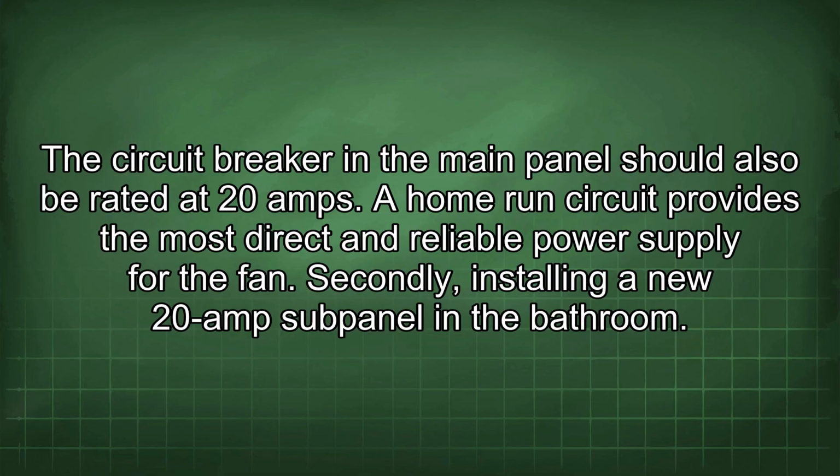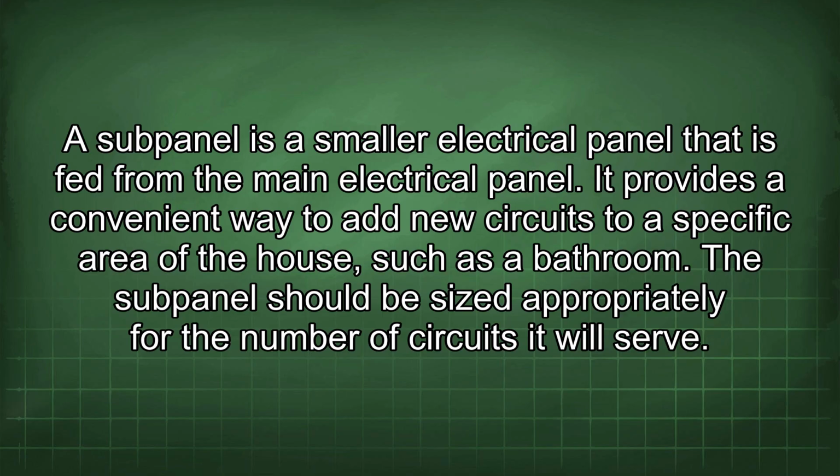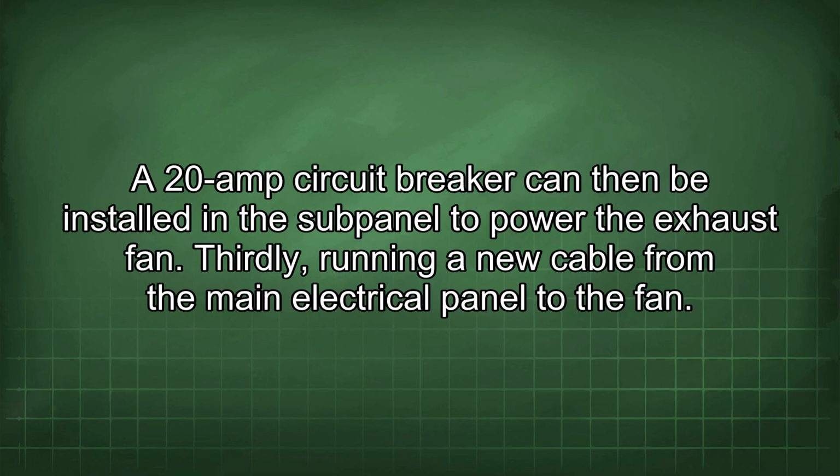Secondly, installing a new 20-amp sub-panel in the bathroom. A sub-panel is a smaller electrical panel that is fed from the main electrical panel. It provides a convenient way to add new circuits to a specific area of the house, such as a bathroom. The sub-panel should be sized appropriately for the number of circuits it will serve. A 20-amp circuit breaker can then be installed in the sub-panel to power the exhaust fan.